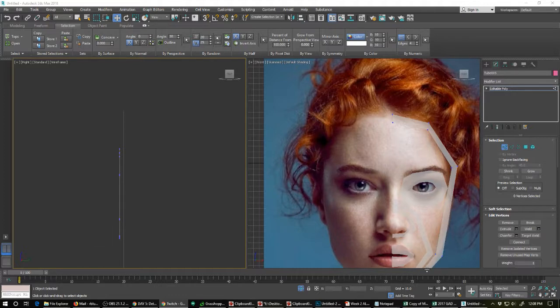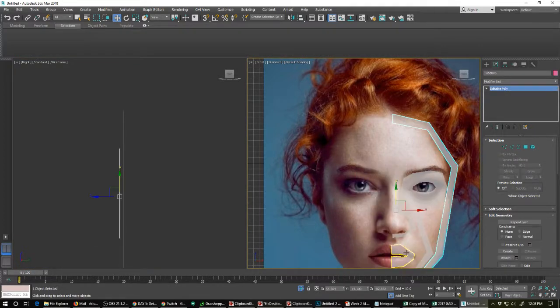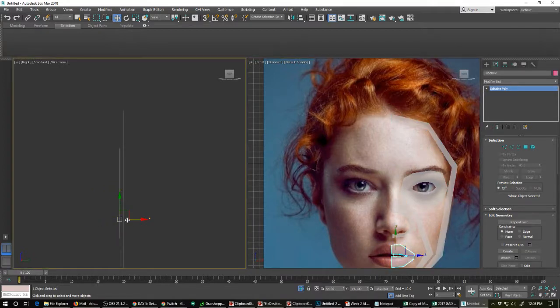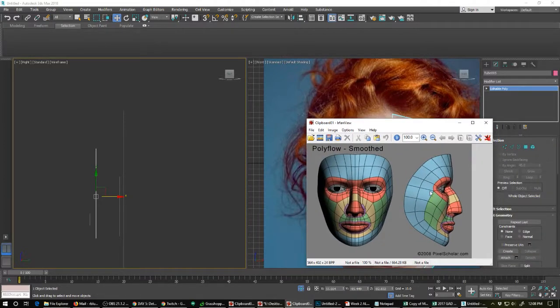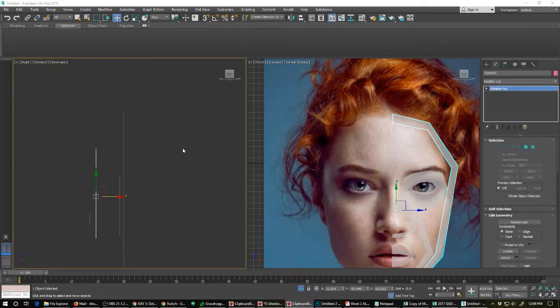with this in mind, I'm going to grab these pieces. So I'm going to go here, top level, grab this. Mouth is roughly here. This edge loop right here is something like this. So what I'm going to do is, looking at this here, I'm going to kind of emulate that, the side edge loop here. So I'm going to basically move that to the front.